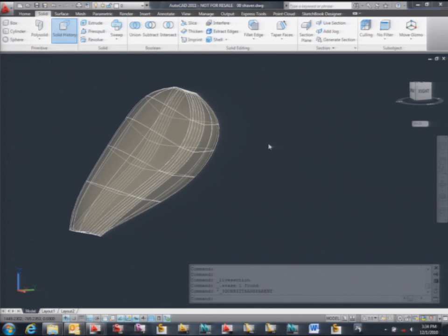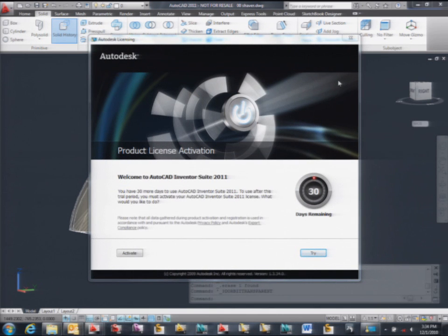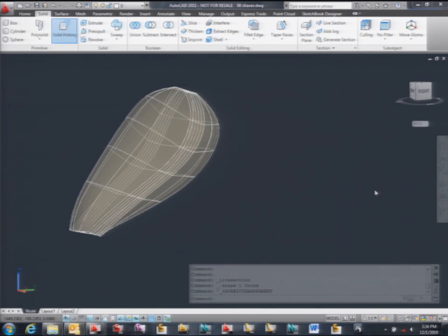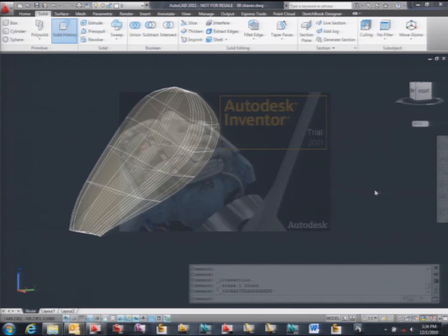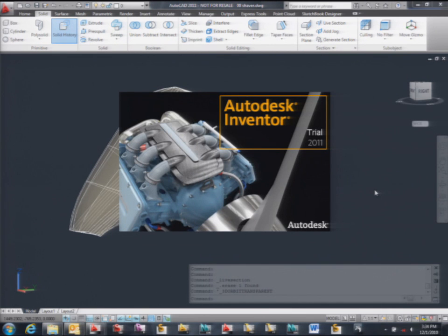If the surface is watertight, can we do Boolean operation on it? Yes, yes. I mean, why would you do a Boolean operation on the surface? Yeah, but you can also do trim. Boolean operations in a surface can be done, but there will not be associativity there.